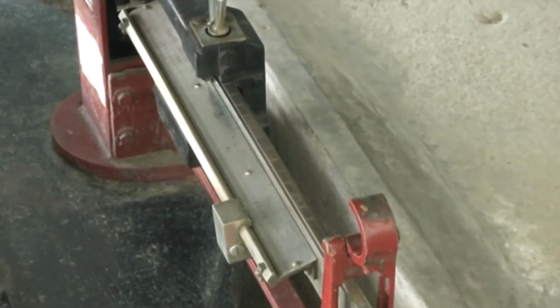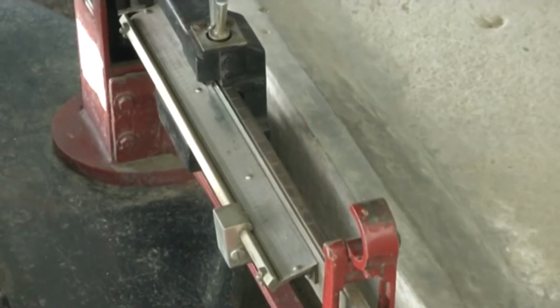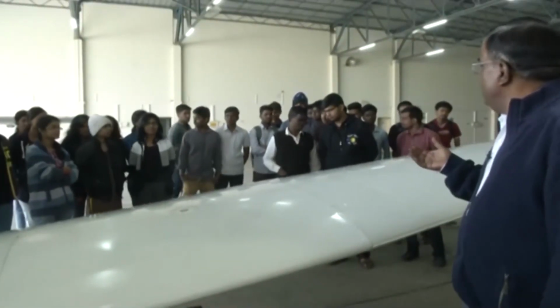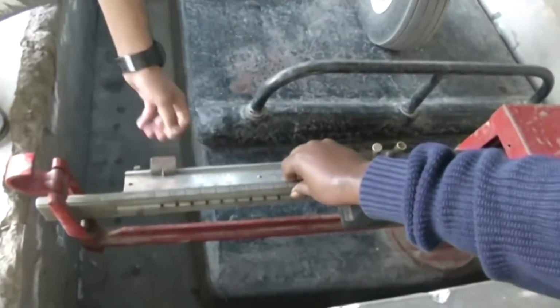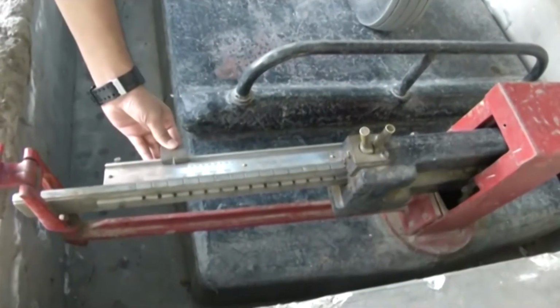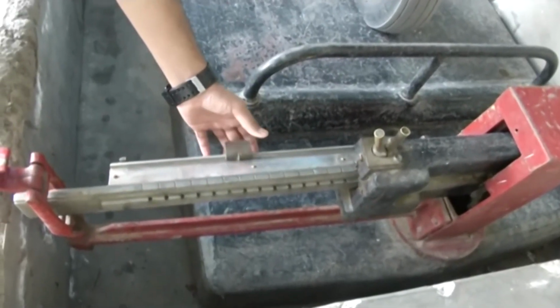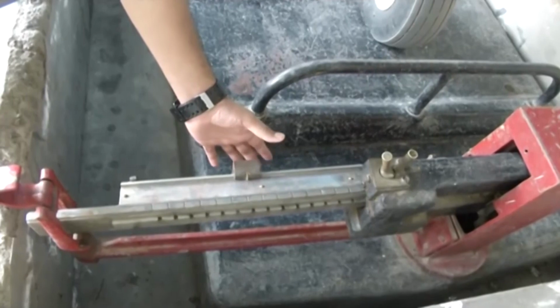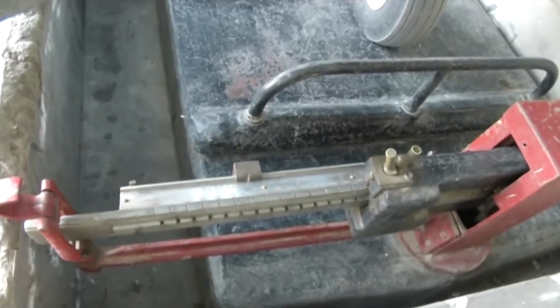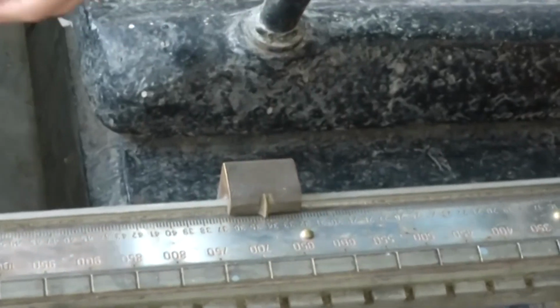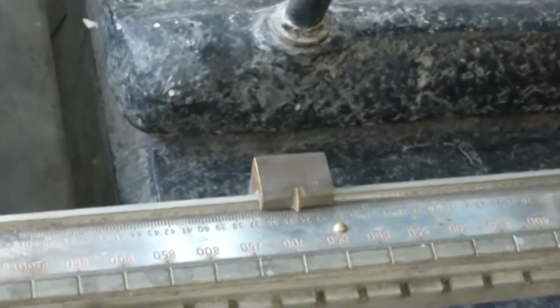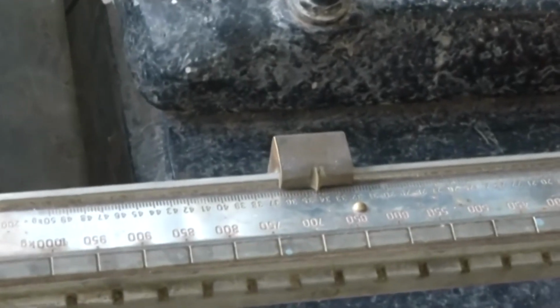Okay. What about the nose? Somebody measure the nose. Come on. What is the problem? Can't you measure? We'll help you out. Come, first disturb the balance. See that this scale is down. We have to somehow make it parallel. So he will try to use the vernier. Do it. Yeah, it's balanced. Can you read the scale now? 650 main scale, sir. So the nose wheel reaction is 684.2 kg.